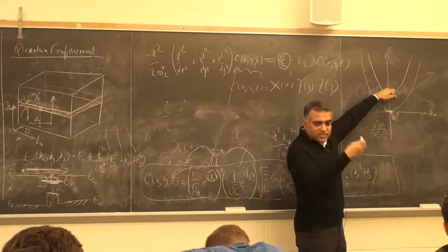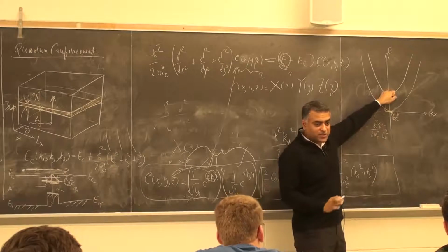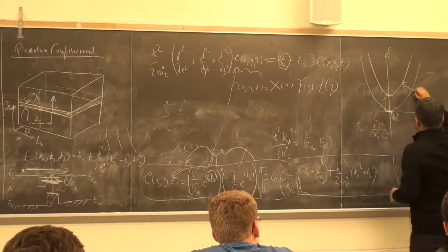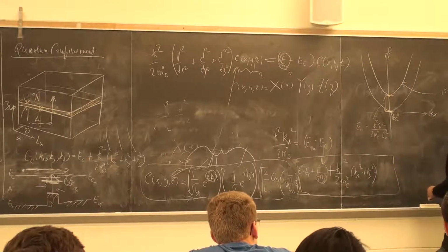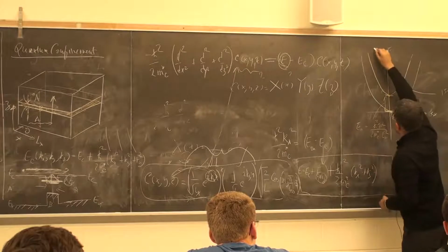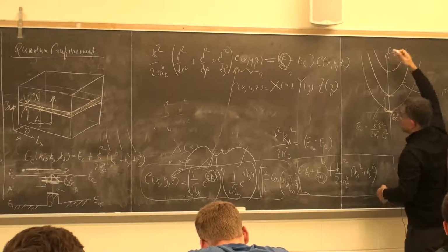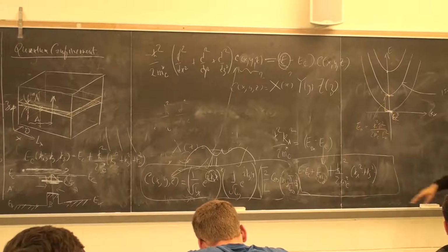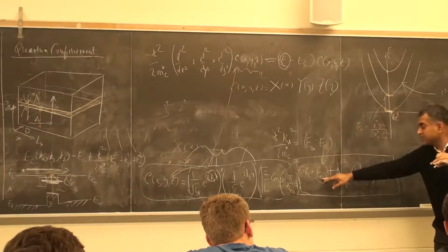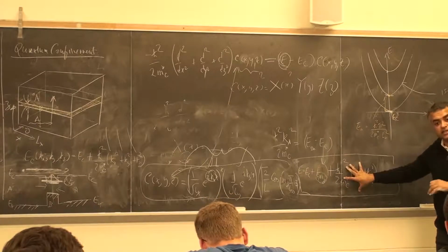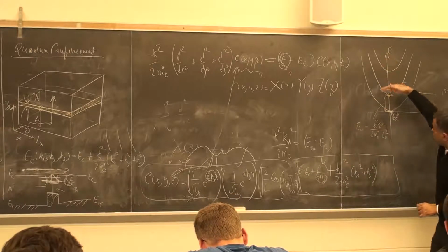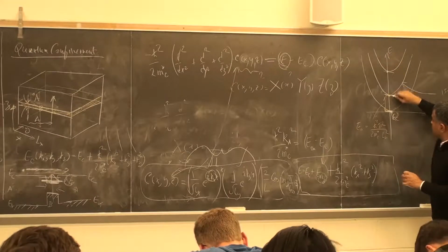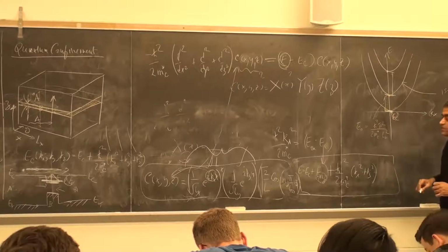What you call it is one subband now. It's not a full band. It's because of quantum confinement in the z direction that you have what we would call a subband. This is the first subband. Similarly, for nz equal to 2, you will have another, and so on. Does that make sense? The second state will be some other state, and so it will shift it, and then this term stays exactly the same again, right? So the curvature stays the same. It's just that the minimum energies shift up based on the quantum confinement, right?